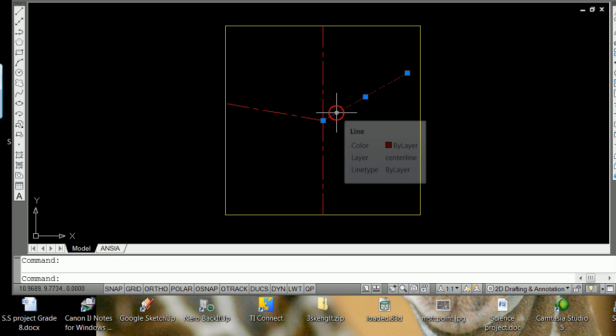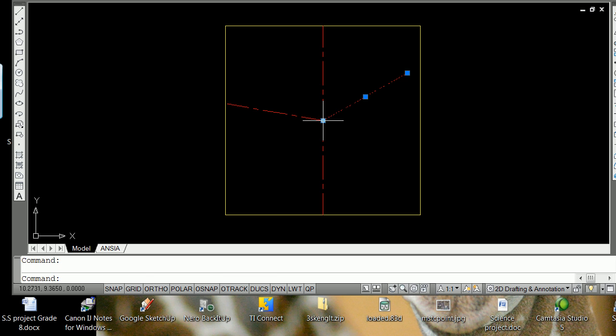I'll do it again. Left click on this one, left click on the end, spacebar, C for copy, 60 degrees. And it went the other way. So I can now just tell it minus 60, and I have that. Now, think about it. I now have two lines, a line upon a line right here, because I copied that back. And so I'm going to left click, and then I can use the erase button here and get rid of one of them, so one is still there.